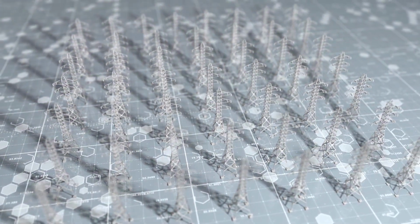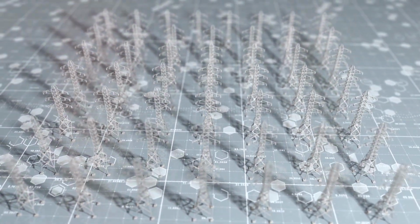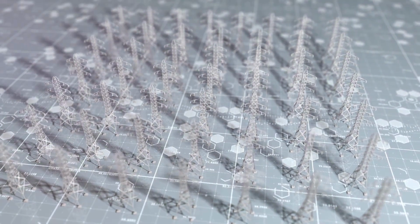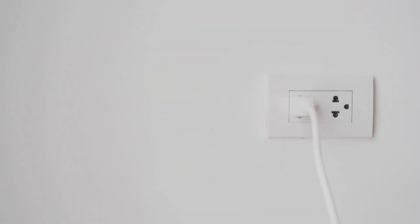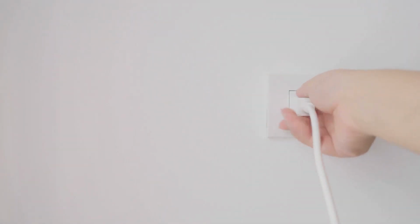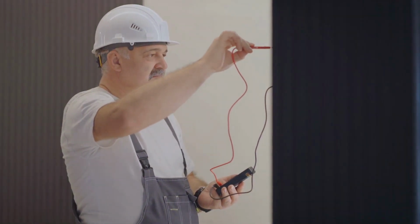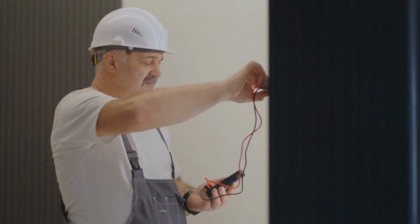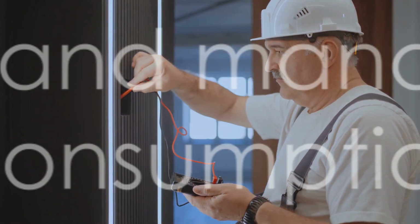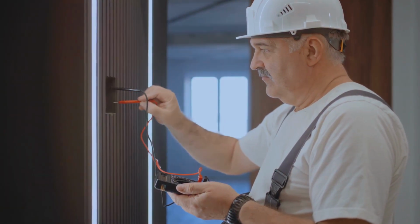First, it's wise to distribute your loads evenly. This means spreading out your high-power appliances across multiple circuits to steer clear from overloading any single one. Second, consider using power strips with surge protection. These handy devices not only distribute power safely, but also shield your appliances from harmful electrical spikes. Lastly, if you're constantly wrestling with overloading issues, it might be time to consult an electrician about upgrading your circuit to handle higher loads. By understanding and respecting the maximum consumption of your circuits, you can maintain a safe and